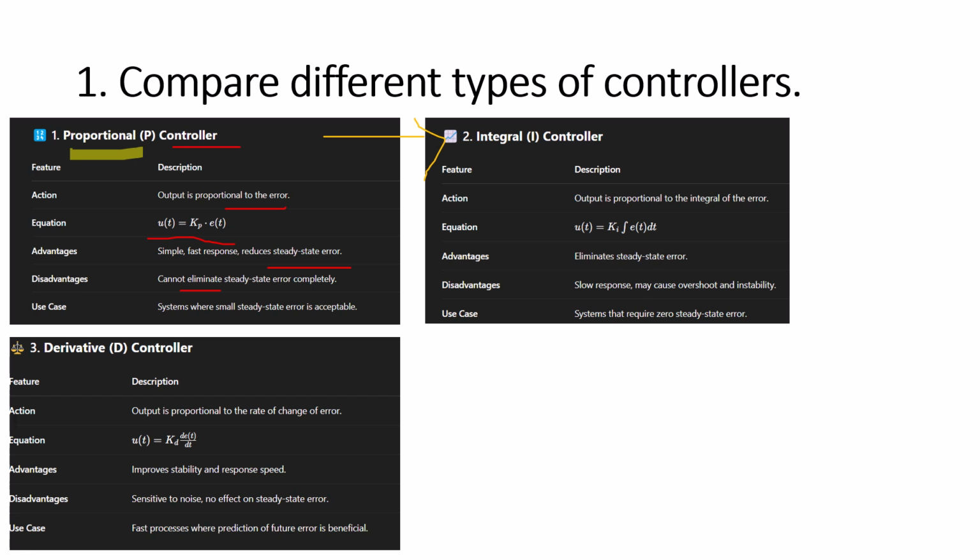search for another controller which is called the integral controller. In the integral controller the output is proportional to the integral of the error. The problem that we had, steady state error that cannot be eliminated, can be eliminated in the integral controller.